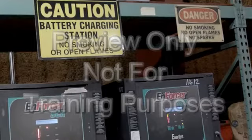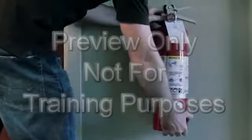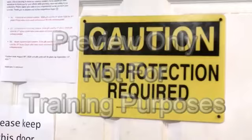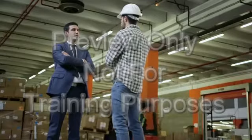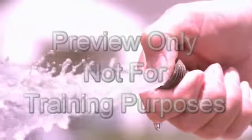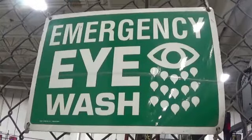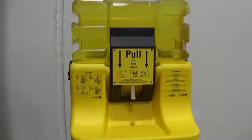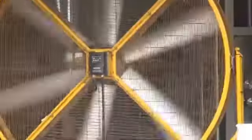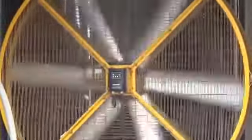Some of the required aspects of the charging area include no smoking and having adequate fire protection available. Pay attention to and follow all posted signs. If none exist in the area, talk to your supervisor. Have ample and ready available water supply for flushing and neutralizing spilled acid. An eye wash station should be nearby along with a first aid kit. Proper and adequate ventilation is necessary to avoid buildup of hydrogen gas during charging.